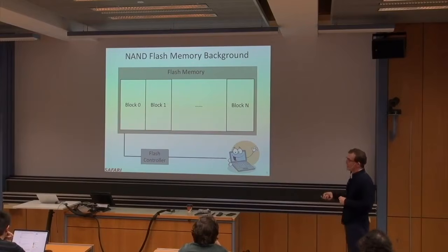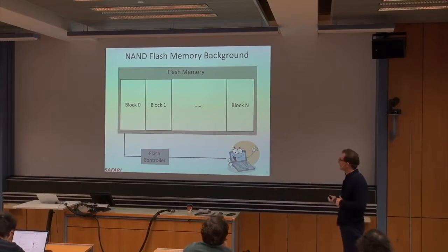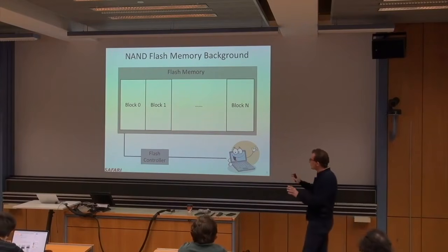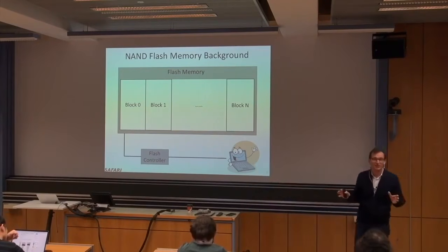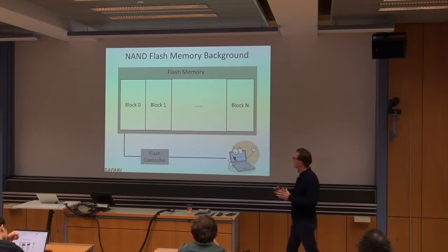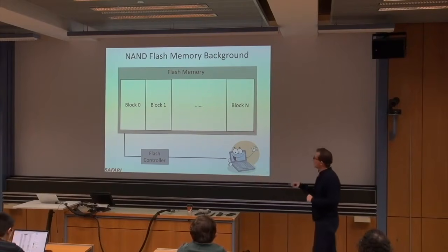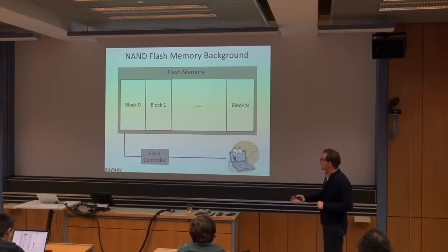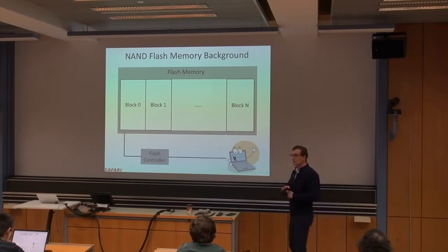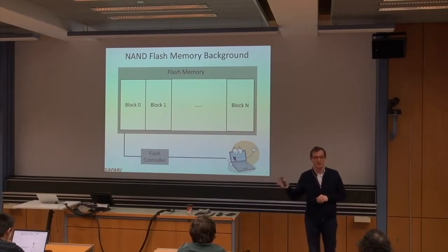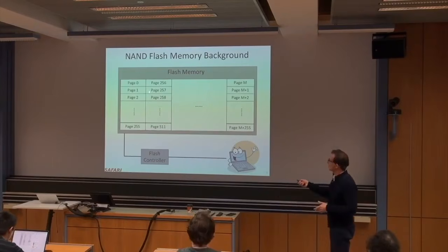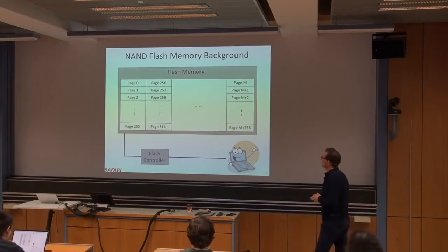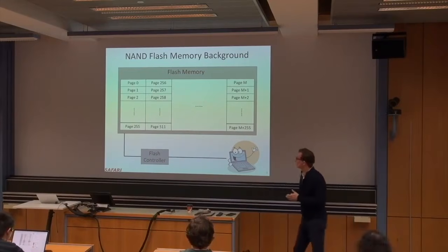Whenever you need to do a write, basically if you want to write something, you initially erase an entire block. So the block erases are done on a block granularity, and that's to minimize the cost of erases. But you can write at the page granularity, and you can read at the page granularity once you erase the block. Erasing means setting the voltage level to the minimum voltage level possible in the entire block itself. So a block can be pretty large. Basically, it can have 256 pages, for example, in each block, and each page is about 8 to 16 kilobytes, for example, in flash memory.